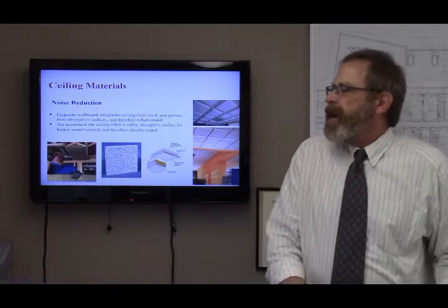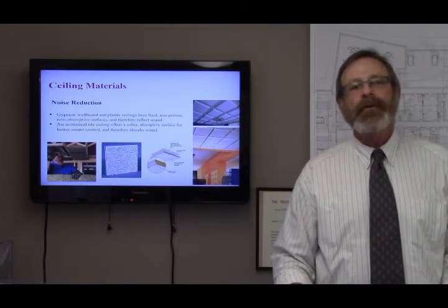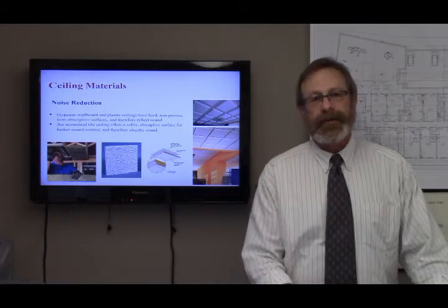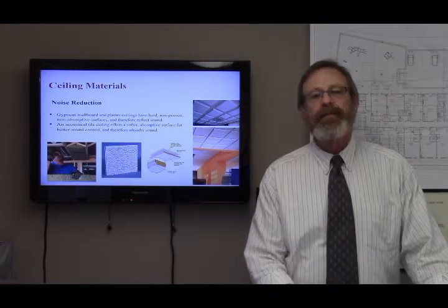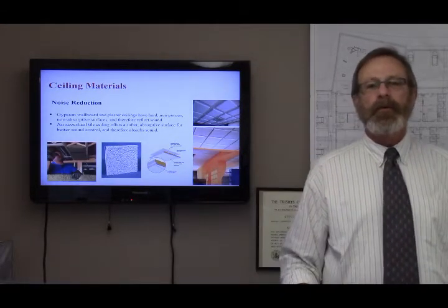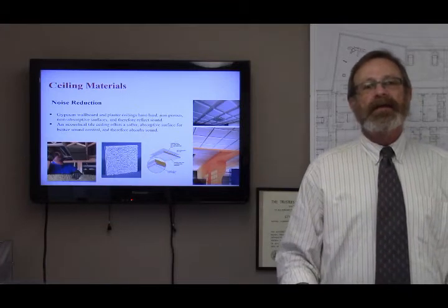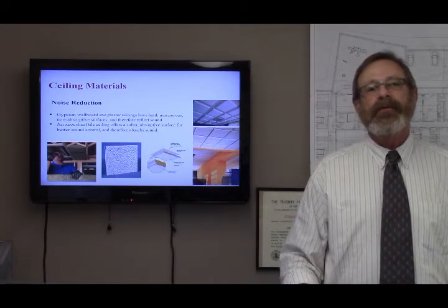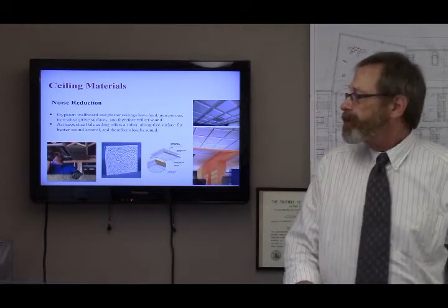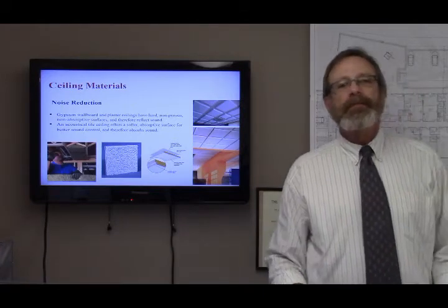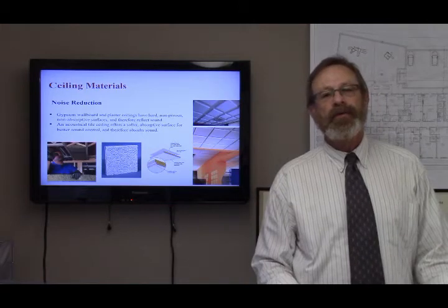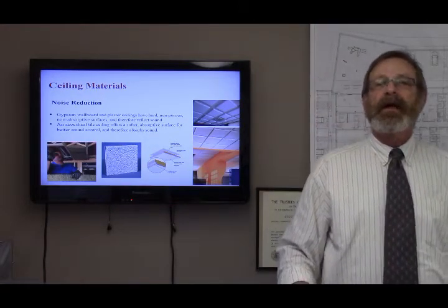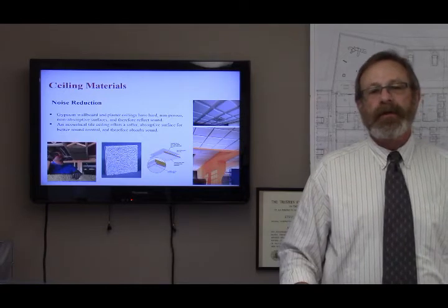So this is a good time to remind ourselves of the impact which surface absorption and reflectivity have on acoustics. Thin panels, such as the gypsum wallboard that we've been talking about, tend to pass the sound through, which limits acoustical privacy in spaces with a shared plenum. Composite materials with acoustical material laminated to a substrate help alleviate this problem.